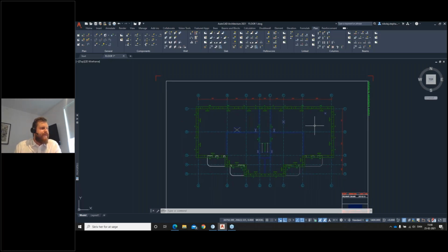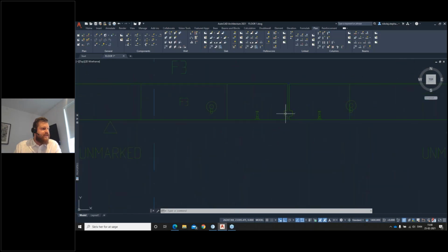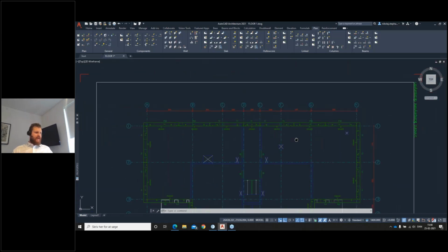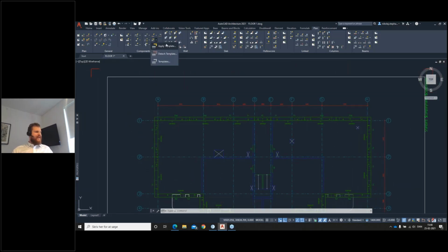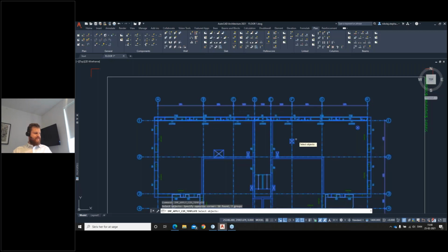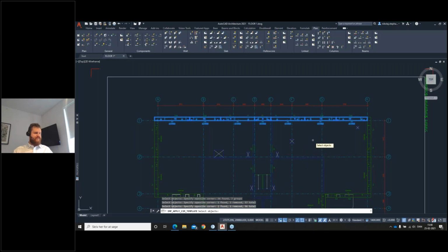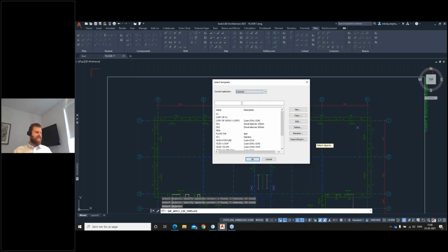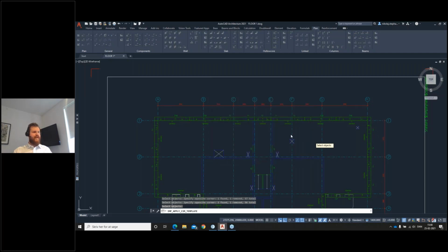So between these connections here, right now, I don't have anything. I want to connect these with wire loops. That's a very common thing to do here in Europe, to have these wire loop connections. And to do that, I have a casting material template. I mentioned the casting material template in the intro before. But for example, I can take a selection of the elements, or all of the elements for that sake. Just say, yes, please select these and add my template. Here I have one I called wire loop. Click OK.